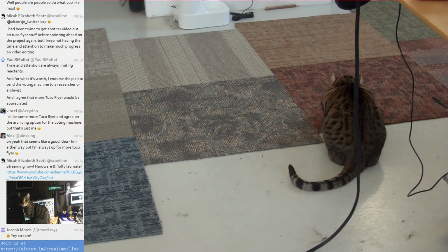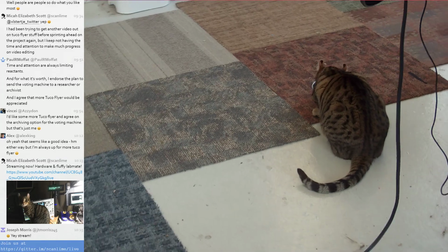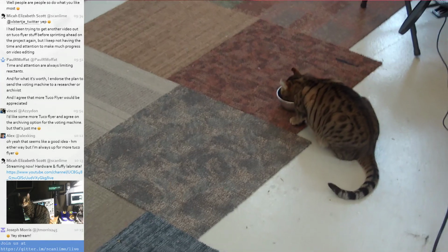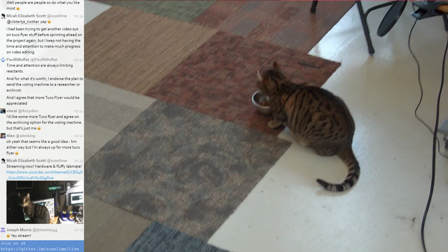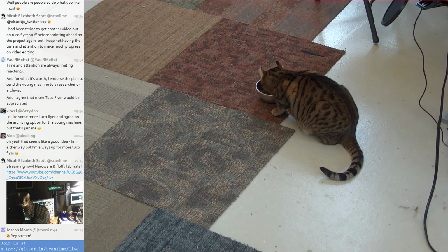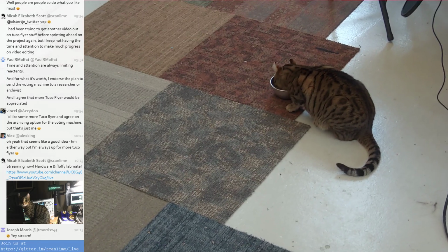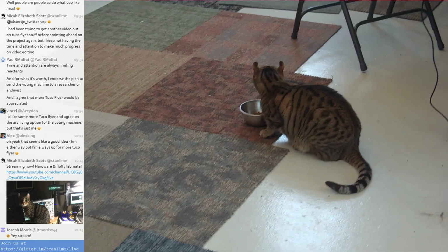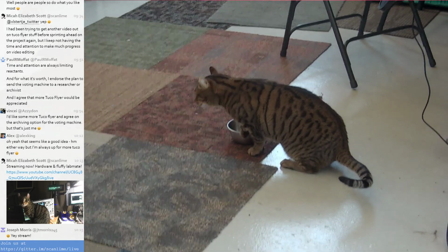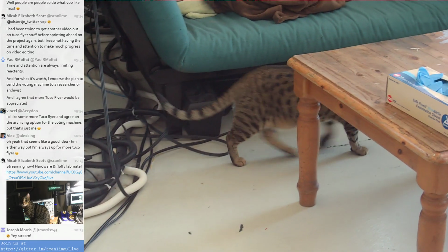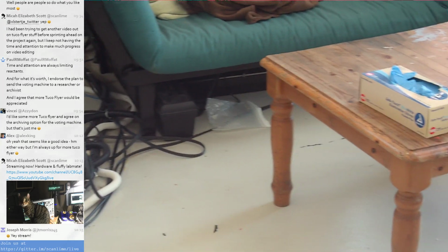I think I have the maximum speed turned up way too high right now. I was trying some experiments, and it's really way too easy to get one of the winches under-tensioned, as is the case right now. If I go fast, the tension algorithm doesn't keep up, and if I go slow, the hysteresis, or the lack of hysteresis, in the winches oscillates. So those are two pretty severe problems.